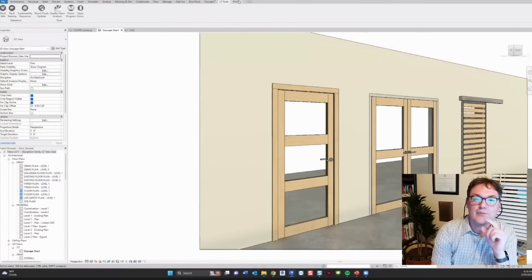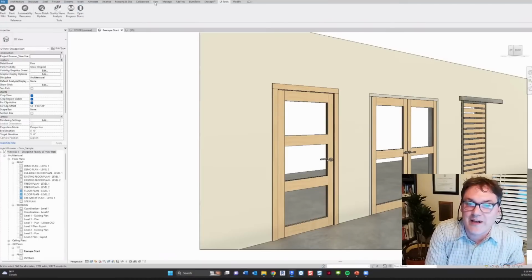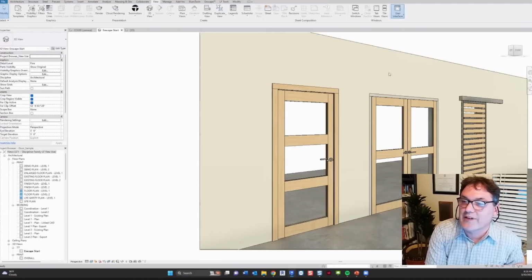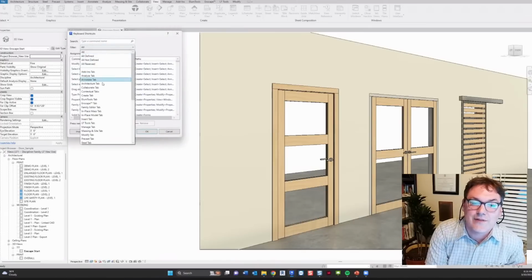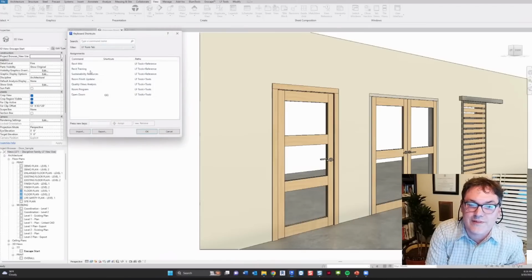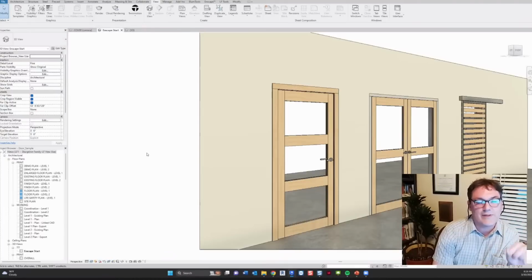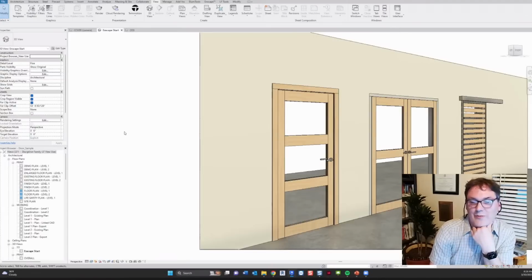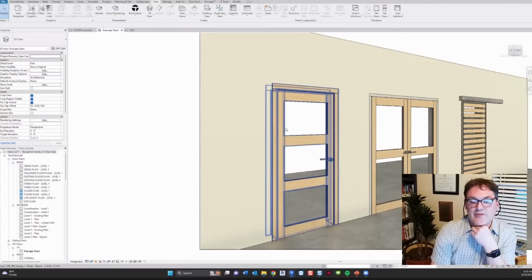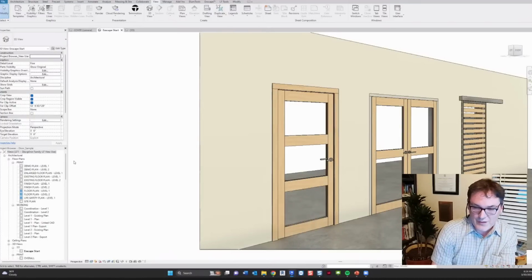The only reason that we made this tool is because when you have an API add-in, you can then assign a keyboard shortcut. If you go to our LF Tools tab, the doors open, I just set to QQ. Only the doors that have the check mark checked open. When I go into the Revit project, a current project we're designing that we got client permission to share, you'll see just the main doors open. We don't want all the toilet room doors opening and things like that.